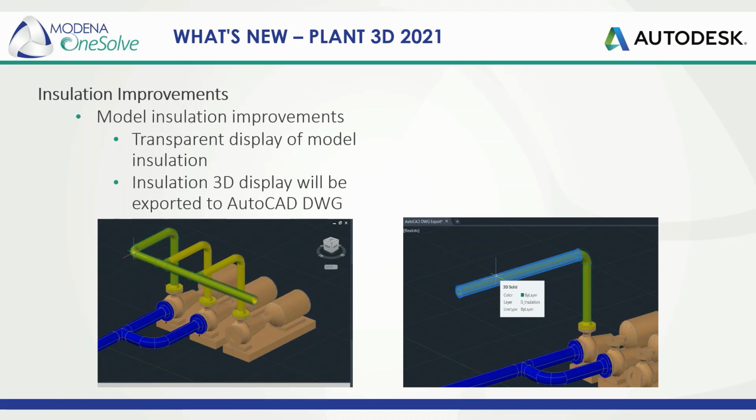easier to recognize. Regarding the installation display for non-Plant 3D users, so for those that are using Plant 3D, obviously this is applicable to anyone using Plant 3D, or at least 2021. If we share this information with members outside of that environment, so if we're sharing outside of Plant 3D to standard AutoCAD users, it will create a 3D solid for that installation display, and it will have a transparent appearance as well. So even for non-Plant users, they can still toggle that installation display on or off using standard layer control settings.